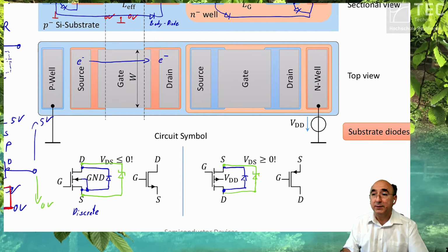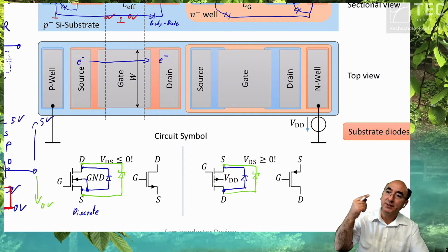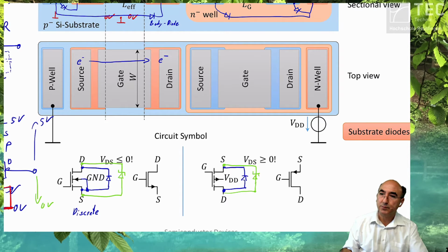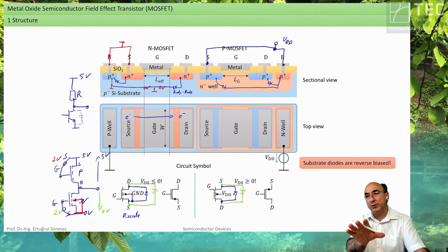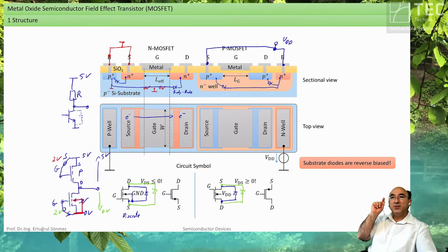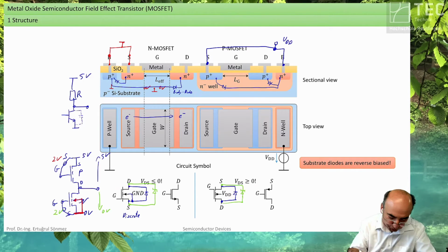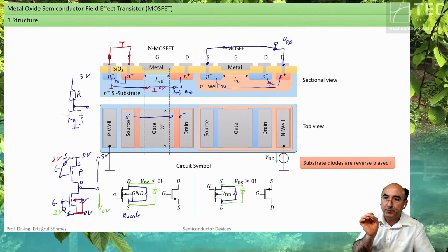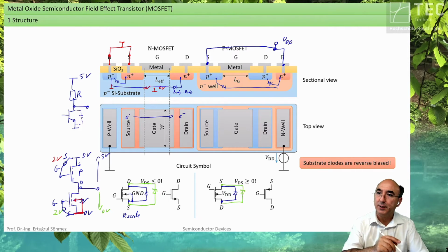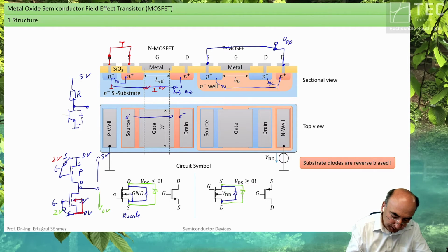Okay, but if you go towards 600 volt applications, now it starts to be very interesting. It's just a story, not the lecture. If you go towards 600 volt applications, then you can use, for sure, MOSFETs also for 600 volt applications. But you don't have anymore a silicon Schottky diode to prevent to switch on these diodes.